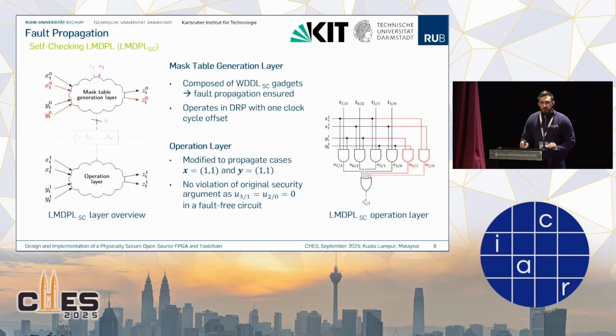And then in the operation layer, we also needed to cover 2 additional cases, namely the cases where any of these inputs is set to this faulty state 1, 1. And if we look at this in an exhaustive logic simulation, then we would see that any faulty state is going to be propagated to the output.